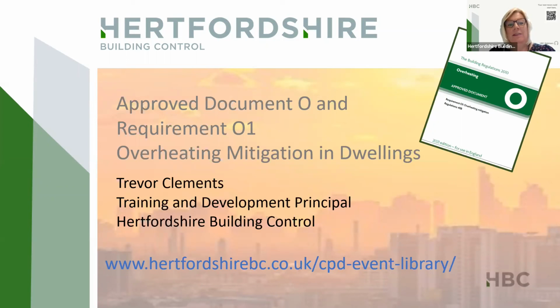Please give feedback on the use of restrictors on high-rise blocks and the effect on ventilation area. Yeah, well, restrictors are one method of making a safe opening for removing excess heat. However, obviously, it does restrict the geometric free area. You have to assume that restrictor is in place, so it does limit the amount of ventilation area you'll get from that window. So yeah, you'll see a lot of that on flats, and there maybe need to be more windows.